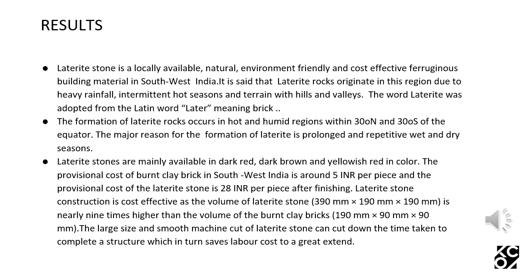Laterite stone construction is cost effective as the volume of laterite stone, approximately 390 mm into 190 mm into 190 mm, that is length into breadth into height, is nearly 9 times higher than the volume of burnt clay bricks. The large size and the smooth machine cut of laterite stones can cut down the time taken to complete a structure, which in turn saves the labor cost to a greater extent.